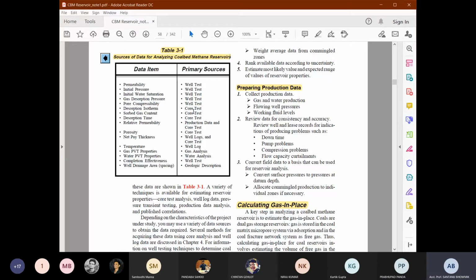And obviously there is always some overlapping. Suppose the distance between two boreholes is 100 meter. If you consider an equal zone of influence from the center of the borehole, that means borehole number 1 has a 50-meter influence to the right of it, and borehole number 2 has a 50-meter influence to the left of it.